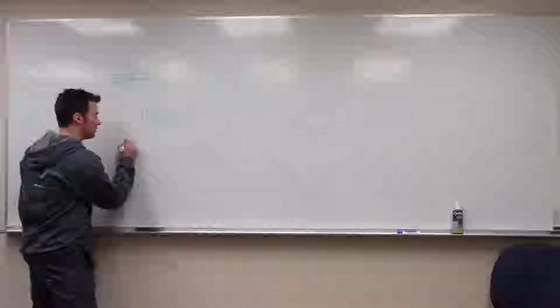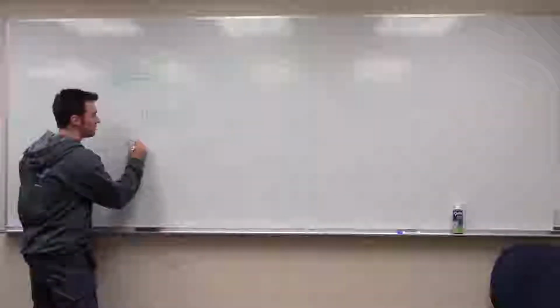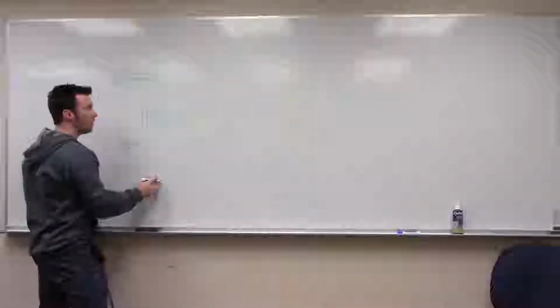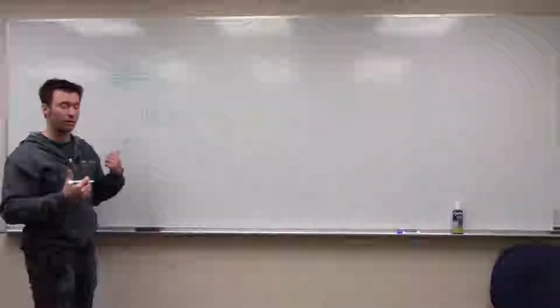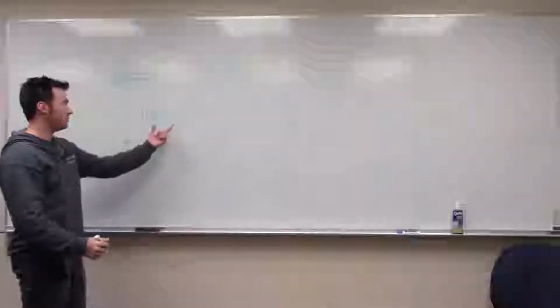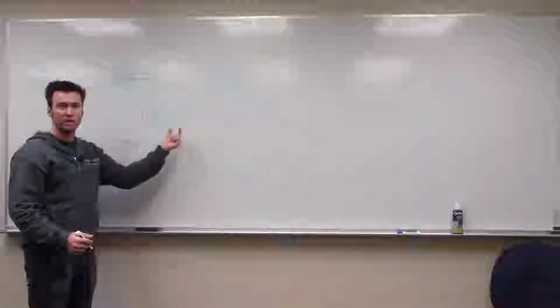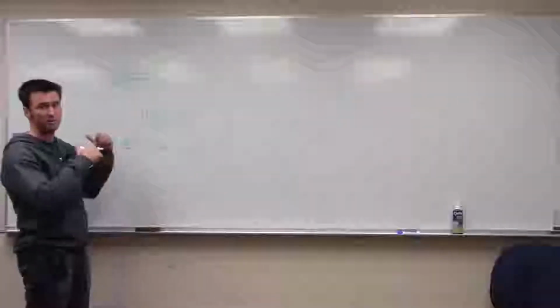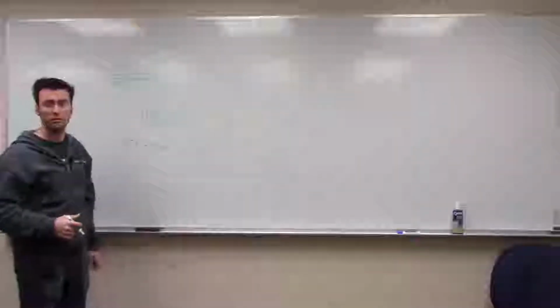I'm just going to invoke Newton's second law. The sum of the forces in the horizontal direction is equal to, well, this kx force is acting in the negative x direction, so I'm going to give it a negative sign here. And this force, c x dot, is acting in the negative direction because left is negative according to the coordinate I've chosen.